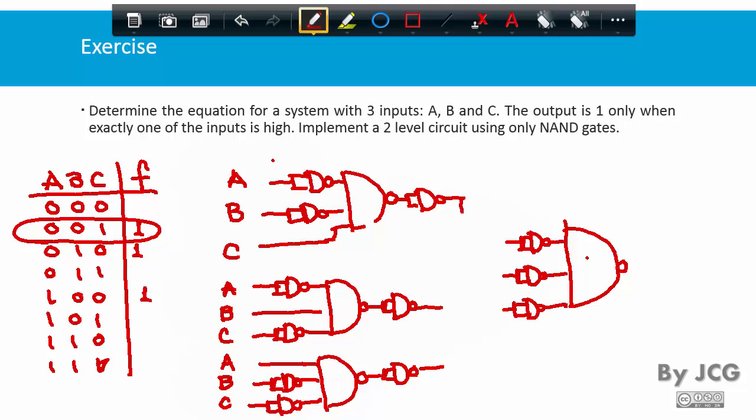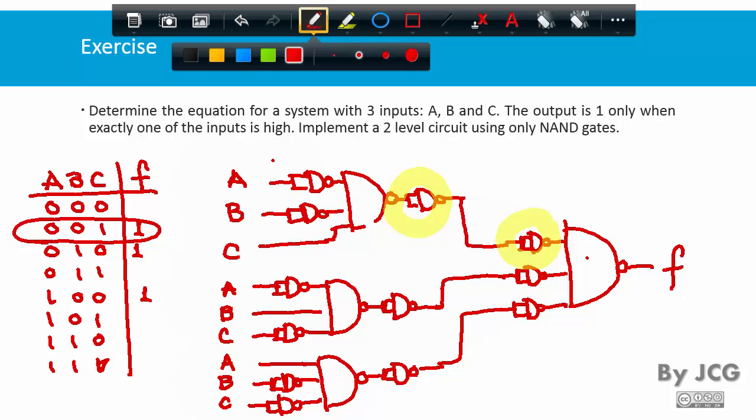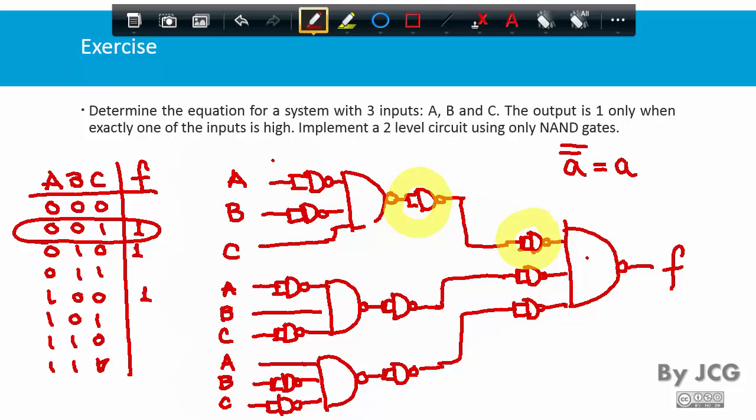Now, the interesting part here is when we connect this. This is the correct circuit. Here we have the function. Now we can realize that both this one here and this one here are inversions. So this is as if I had two inversions in a row. If we have A inverted, inverted, then we have A. That means I can cross these two because there's no need for me to do the inversion twice.